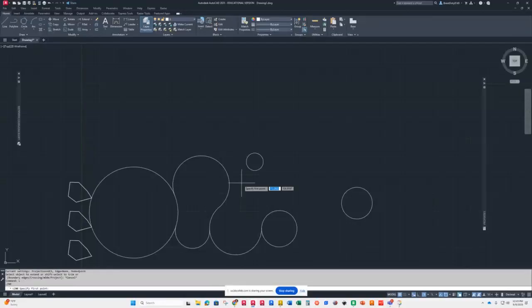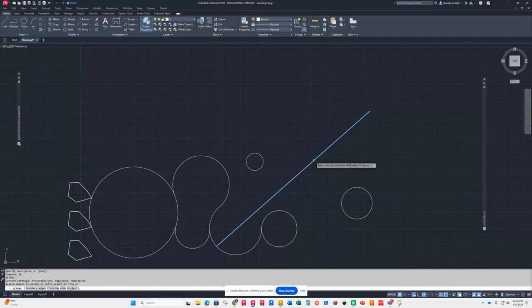Well, okay, so what if I draw a line? And I draw me a line from here to there. Now, if I go into extend, then I can just pick the line. Whatever end of the line is going towards where I want it to go. So it has to be over the halfway part. And then I can just pick. Now extend, I typically don't pick where I want it to go. I mean, you can, especially if you have to go through three things to get there.